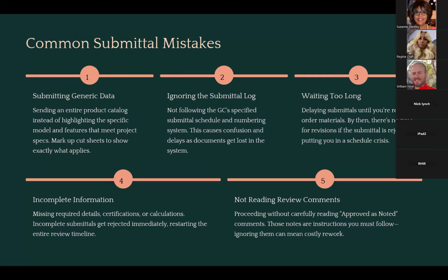So you don't think about putting your submittal together until it's about 2 weeks before you have to be on site. And then the general contractor says, hey, I know you're about to be here, but you haven't given me your submittal yet. You give that submittal to them, but it takes 8 weeks for that review to get through. Well, when it's time for you to show up, you can't go by that because you hadn't gotten your submittal approved yet. So you got to make sure you understand the process and you get that in as early as possible.